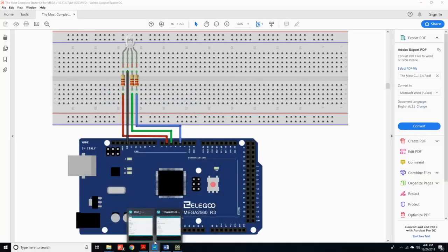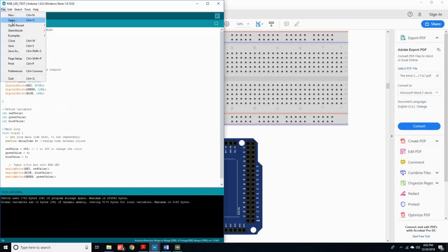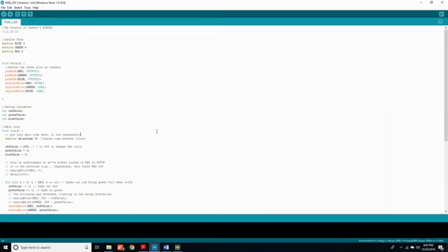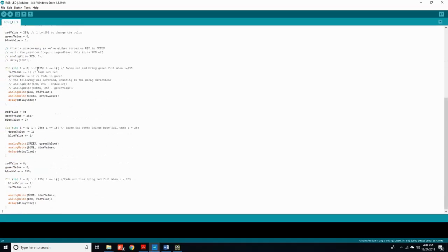Basically, what I did was I took this file, Open, Recent. This is our base, and you should use something like this. I'll put the link to this script in the description, but use something like this first and just upload this script to your Arduino first, just to make sure that your setup on the Arduino is correct before you start messing with TouchDesigner. Because if you start messing with TouchDesigner, you're not going to know what's wrong. Is it my setup on the Arduino, or is it something I'm doing in TouchDesigner? So just go step by step. First things first, set up your Arduino, then put in a simple script that you know works, and I will give you this script in the description, like I said.